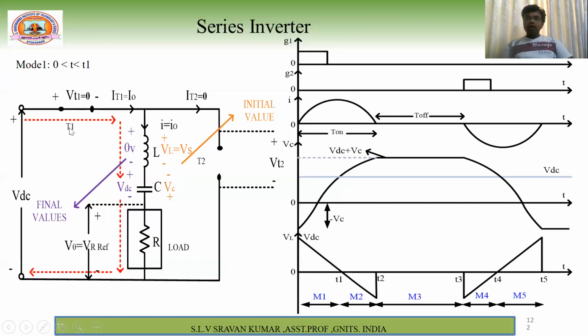off. To turn off your SCR, two conditions must be satisfied. One is the current reaches zero, another is reverse voltage. But here at the instant of t1, both voltages are exactly the same. It's not a reverse voltage, it does not appear. And what about the current here? Maximum. So both conditions are not satisfied, and that's why your device is still in the on state.